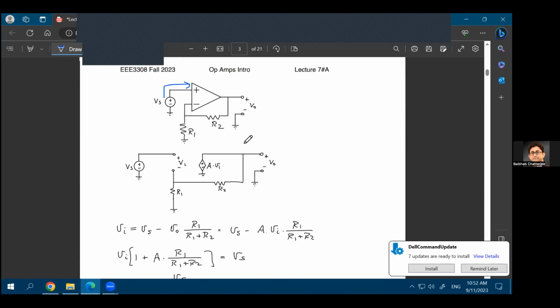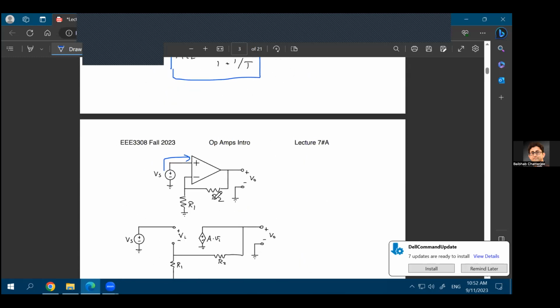So what you have is basically the resistance R2 equal to 0 and the resistance R1 equal to infinite. Because if you just want to short these 2 points, your R2 needs to be equal to 0, right? And because this point is not connected to ground anymore with the R1 resistance, it's another equivalent way of saying that the R1 resistance is very, very high, ideally infinity.